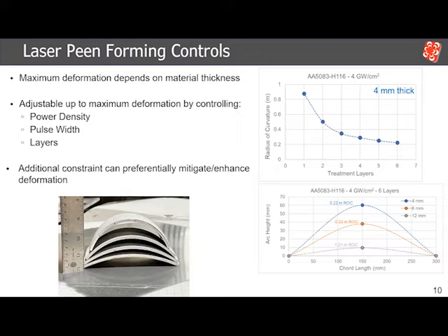If we need to, as I mentioned, there are some alternatives in laser peen forming because we're creating a multi-curve process. We can actually add some other constraints into our system that could get these a little bit tighter. And in some ways, it's cheating as the process capabilities. But by pre-straining the material, you're actually able to increase the capabilities of the process as well.